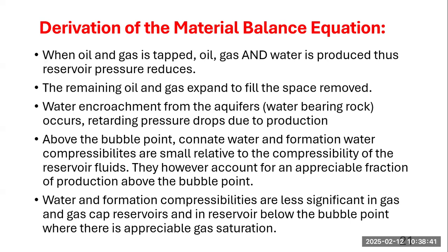So it is a form of drive. There is an influx of water from your aquifer to fill up the pore volume left by production of oil and gas from your reservoir. The spaces left in the microscopic pores are filled in by the water from the aquifer.